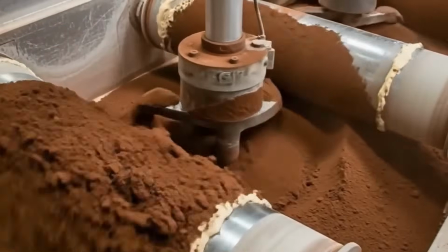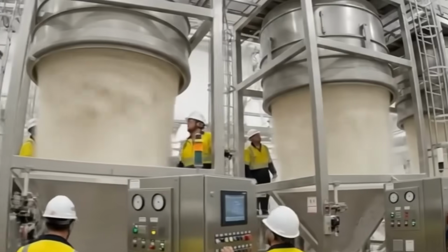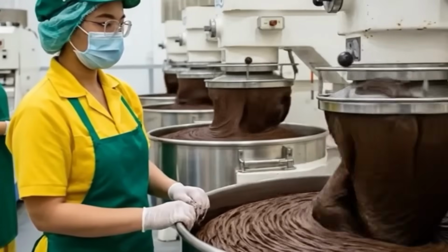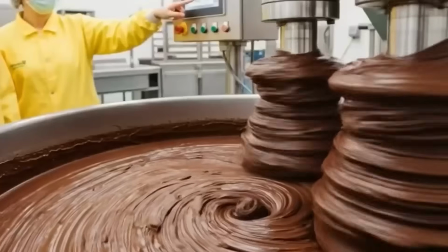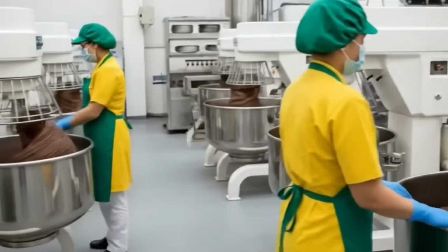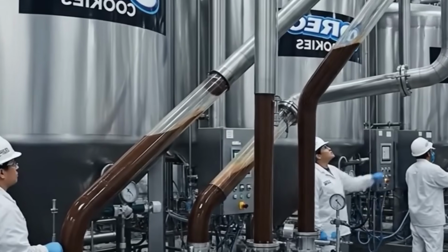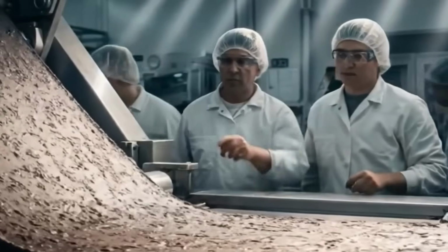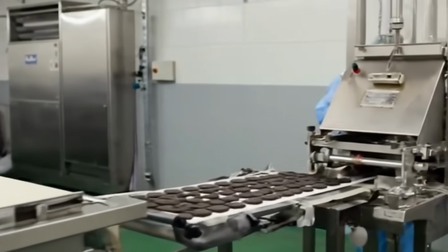Each wrapper is printed with batch code, timestamp, and best before date using thermal inkjet printers synchronized with the machine cycle. Wrapped products are conveyed to a cartoning unit, where robotic arms pick and place the flow-wrapped units into pre-formed cartons. Cartons are constructed from pre-creased flat blanks that are folded and glued using hot melt adhesive. Carton fill confirmation is performed using weight sensors and machine vision.